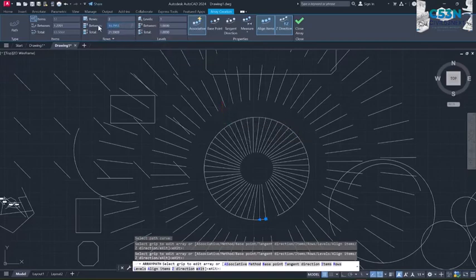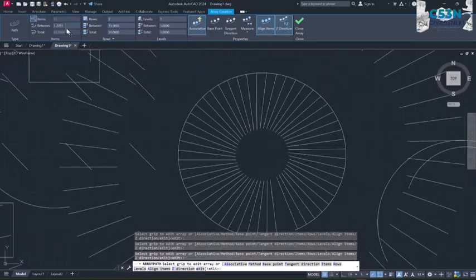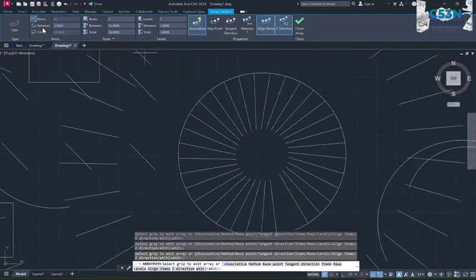So let's give it a distance of, let's say 15, enter. And this one represents the distance inside the circle, inside this curve. So let's say it is 2, type 2, enter. This one will be automatically calculated similarly with this one. Now to end command, press escape.